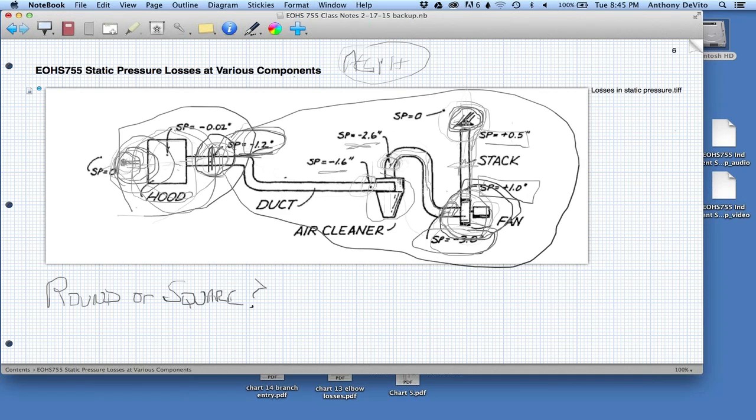Okay, you normally don't want to see those on exhaust systems, because if you can imagine, you're pushing air up here, and bang, you run into this device right at the top. It does two things. It reduces your static pressure. It introduces a loss, right? So it inhibits air moving through this fan and reduces your static pressure on this side.